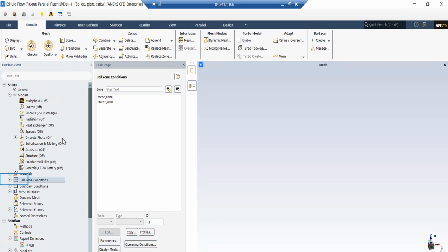As a good practice, it is advised to start the transient simulation with a previous steady state simulation which is converged with a situation close to our transient simulation. For this specific simulation, to simplify our convergence, we could start with a steady state frame motion setup, and after we've reached a satisfactory partial convergence, we could copy our frame motion simulation to a mesh motion simulation using the copy option inside the cell zone.